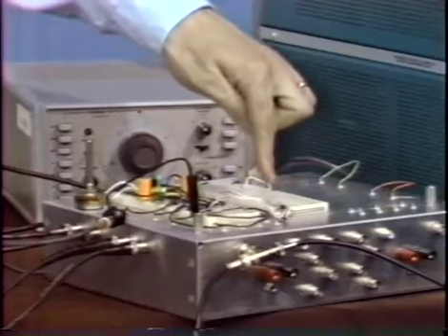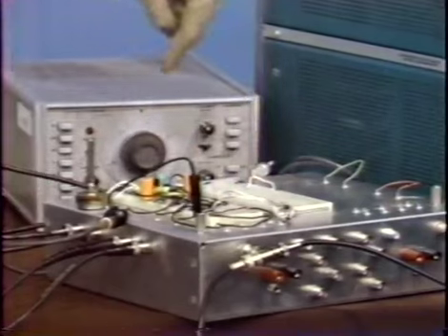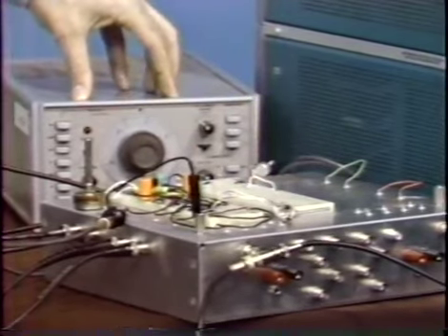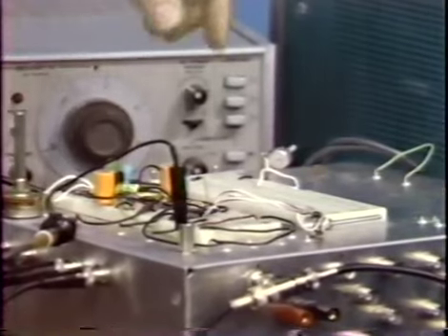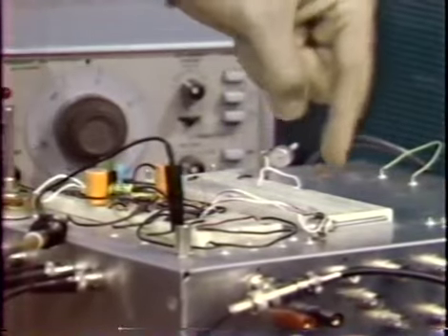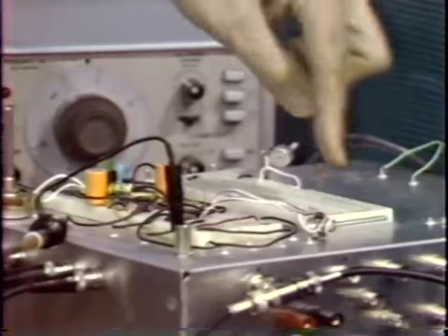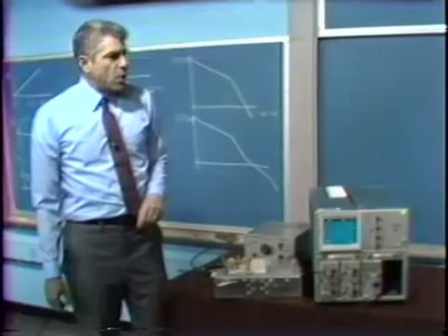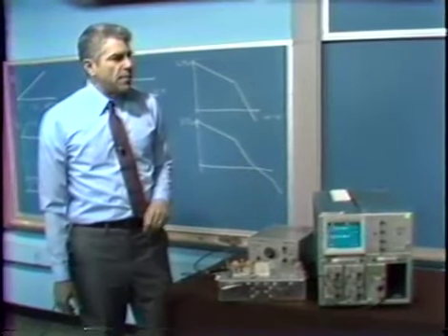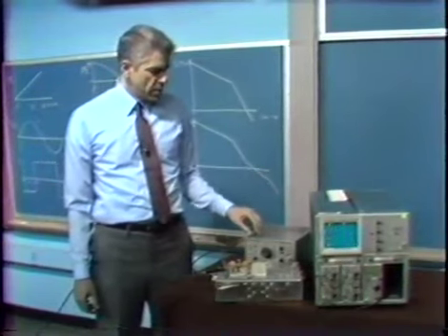And here we have a signal generated again on our little test circuit that we can use to frequency modulate the generator that's providing our command signal. The amplitude of the signal driving the frequency modulation input on our input generator can be controlled with this potentiometer. And what we see now is the commanded signal applied actually to the voltage-controlled oscillator.